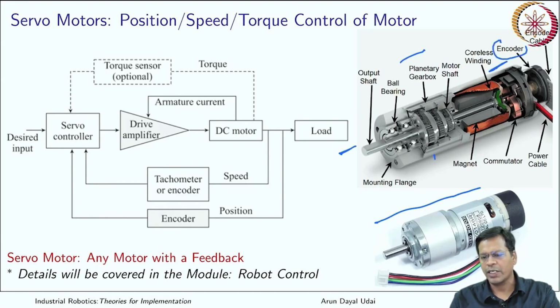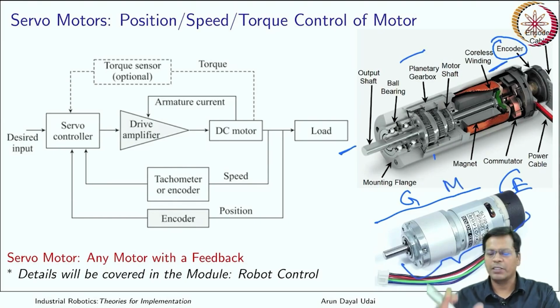Now you have what is known as an encoder, which can sense the angle and give you feedback. So you have an encoder here, a gearbox here, and then a motor here. Overall, this set makes it a servo-motor-capable device. This is a motor with some attachments, so it is not a servo unless it is controlled by some means. So this is a typical servo motor.